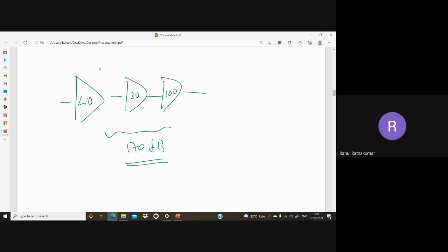Okay, so we express amplifier gains in decibels because of this reason. Instead of using big numbers like 10 raised to 6, 5 into 10 raised to 23, or whatever, which is much more difficult, it is better to have a simplified logarithmic scale. We can add those gains. So if I add a new amplifier here, I am just concerned with what is the dB, say 20 dB. So this net is equal to 20 dB. It's much easier. So the total is 190 dB, something like this. So this is much simpler for the calculation in terms of amplification.